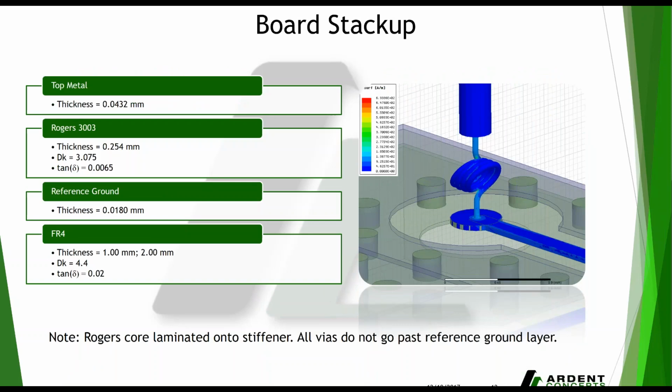This next slide is just showing you the board stack up of our evaluation boards themselves. We use a 3-layer Rogers 3003 board with an FR4 as that bottom third layer, mostly there for rigidity. Rogers 3003 is used for a few reasons. Not having glass weave incorporated into it allows less jitter than found in other materials. The lack of weave also allows tighter and more consistent phase length skew. Lastly, the relatively low dielectric constant of 3 allows for better and higher frequency testing.